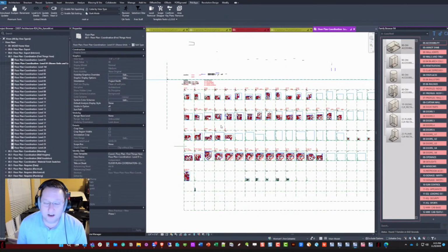And that's because a client suggested it after we were discussing the fact that we all forgot that Revit has some really nice functionality where all schedules can be filtered by the elevation of the levels. And we completely forgot that. So you can tell an appliance schedule, don't schedule anything below the basement. And then you don't have to do any crazy filters to remove stuff that's in the cloud and put that filter in every schedule. You can actually just tell every schedule, don't count anything below basement level 5, and everything in the unit cloud's automatically removed.